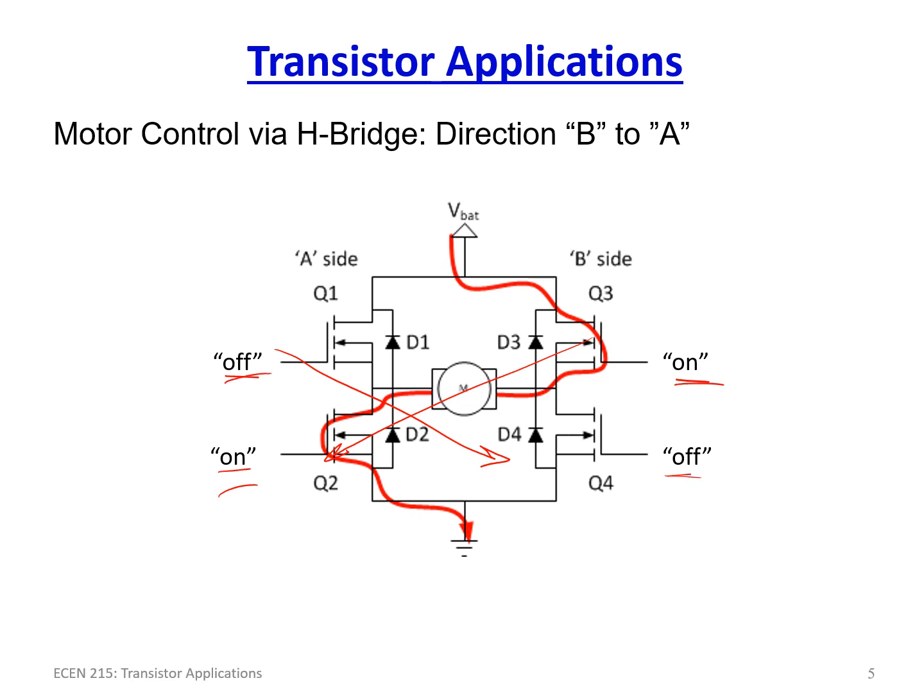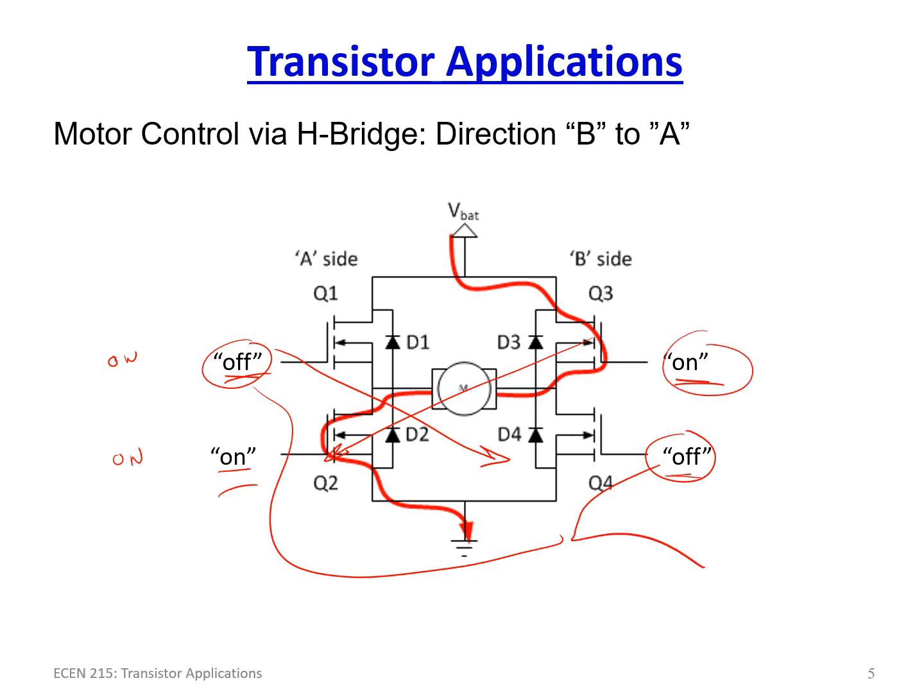And there's usually special chips that you can use, special digital logic circuits that are designed so that if they decide to blow, they blow in a way that causes a fail-safe application where no matter what, you're never going to get a situation where you have an on and on condition. So again, this signal and this signal are linked typically, and then this signal and this signal are separate.